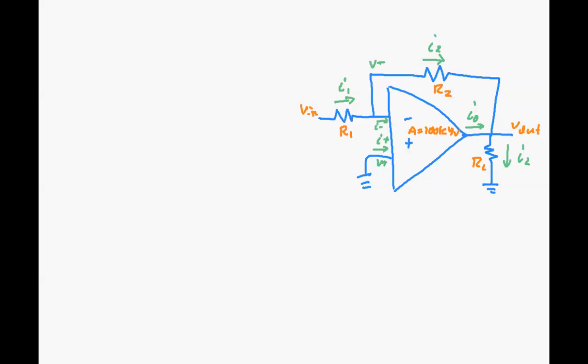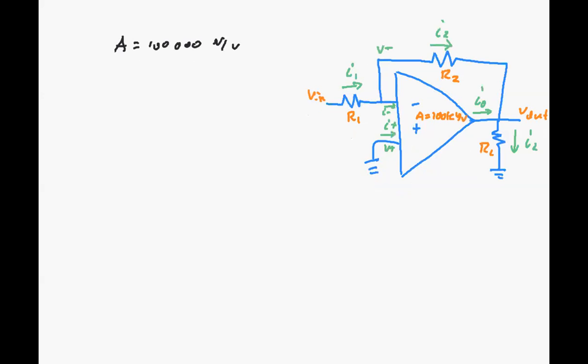So another example from the op amp is when we have a non-infinite gain. If we have a gain equal to 100,000 volts per volt, what are all the currents and voltages in this amplifier? We could have a reference voltage instead of ground on the non-inverting input, but it doesn't really show anything different. The main thing I want to show is what that voltage on V minus is, and how the response of this system changes.